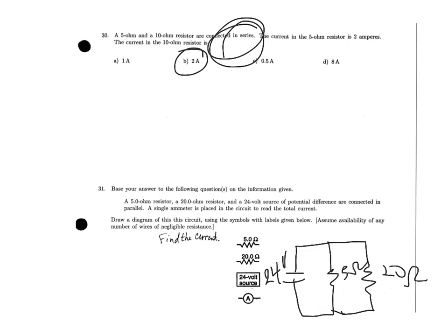And we want to put that ammeter in somewhere. Now, critically, the ammeter cannot go here or here because those are individual paths. So we have to connect it in a spot where the paths are merged, which means we could either put it here or we could put it here where those paths are merged. We just can't put it on an individual path. Okay? And that would be the thing.